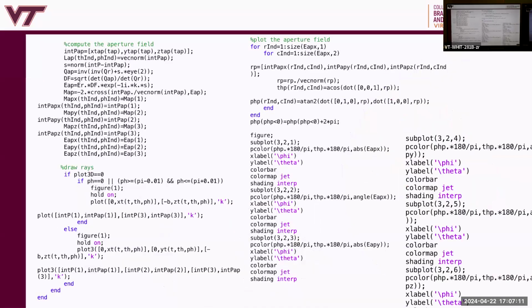Okay, good. So once you use this code and do your homework problem, that's a significant achievement as well. Your 3D method of moment problem is a super good achievement. And this is also a super cool achievement. You're calculating the geometrical scattering. This is how people used to do it. They used to launch rays at the subreflectors, trace them to the main reflector, calculate physical optics current, and integrate that to go to the far field. But now you have computational power, you can probably do the whole thing. But still, maybe not. If it's a big reflector, there's no way. So you got to do ray tracing, right?